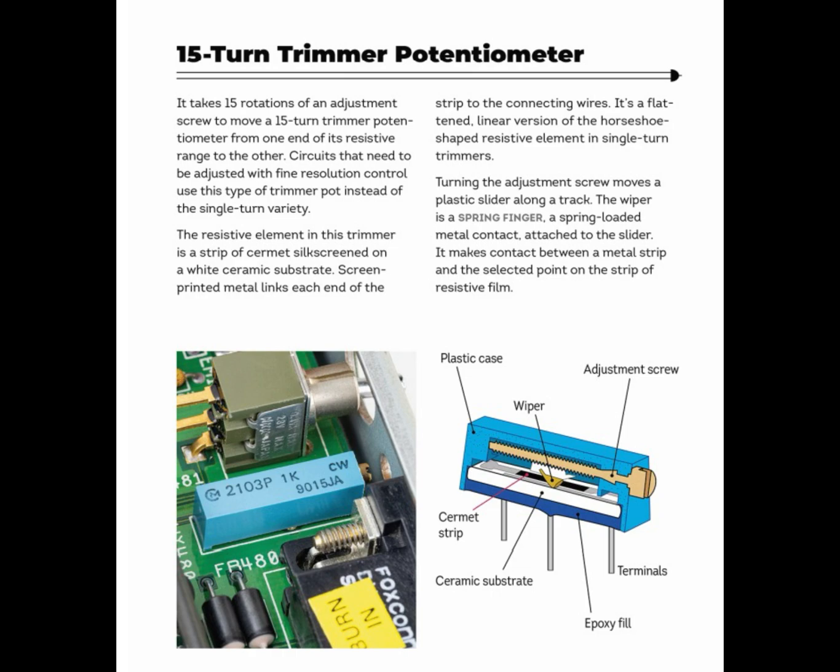Now, it is constructed of, number 1, usually a wiper, the moving contact that slides along the resistive track. Number 2 is the resistive element, which is made from material like carbon, cermet or metal film, which determines the resistance value. Number 3 is the housing, typically encased in a durable material to protect the internal components. Number 4 is the shaft, the part you turn. It has a gearbox to allow for multiple turns.